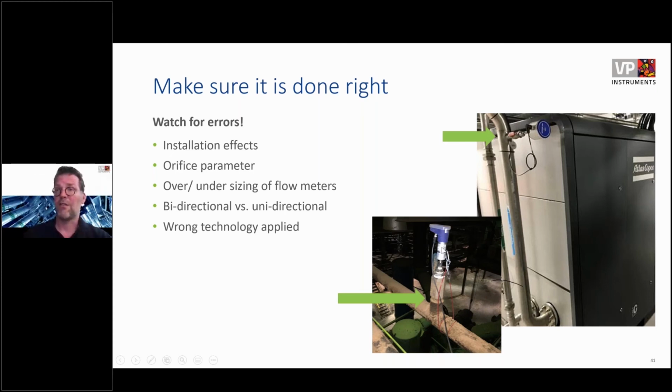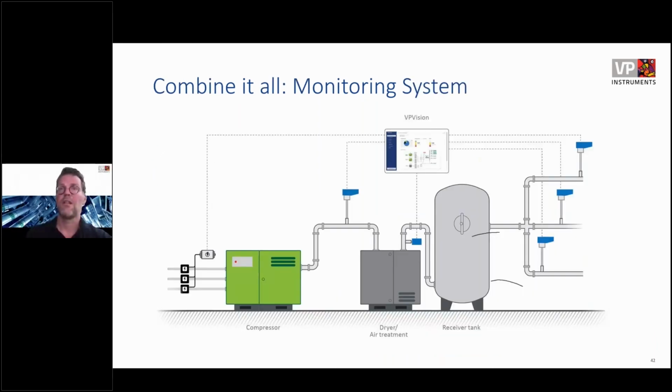And here you see a differential pressure flow meter in a T-piece of equal size, so you get a lot of turbulence around it. That can also affect the measurement. If you want to know more about this, we have a separate presentation on how to install and how to select the right technology. So feel free to contact me after this webinar about that specific presentation.